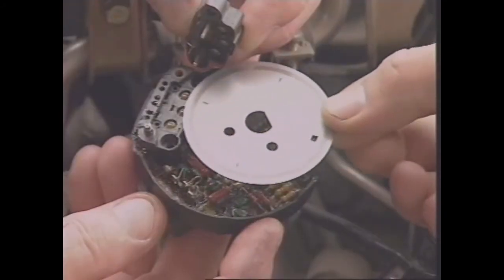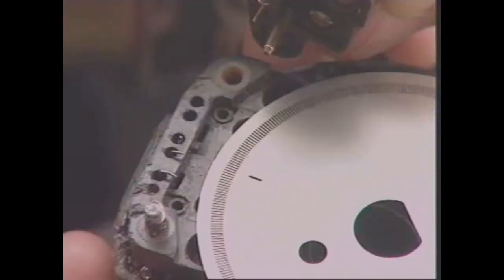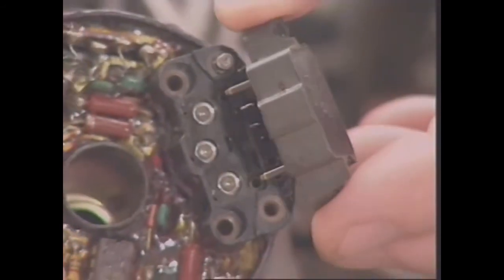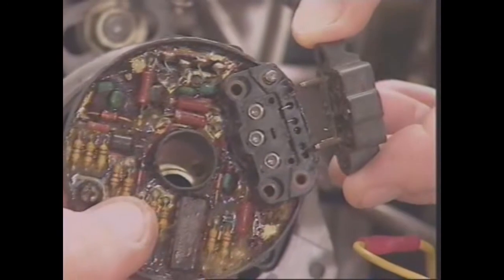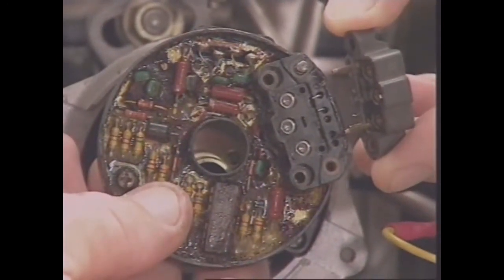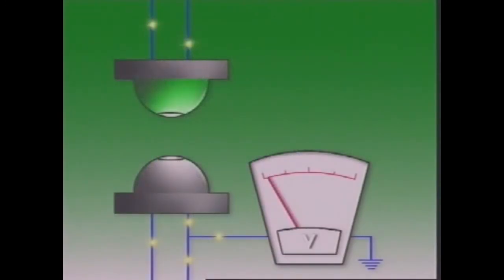As the rotor plate turns, it passes between 2 sets of diodes positioned in line with the slits. The diodes above the rotor plate are light-emitting diodes, while the ones below are photodiodes. When provided with a suitable voltage, light-emitting diodes transmit a fine beam of light. Photodiodes receive this light and use it to make a voltage output signal.